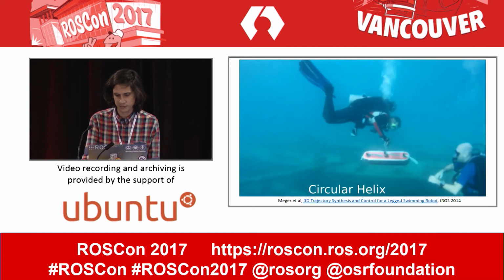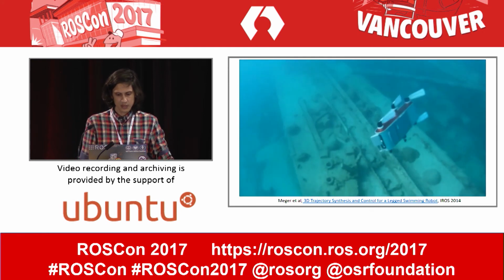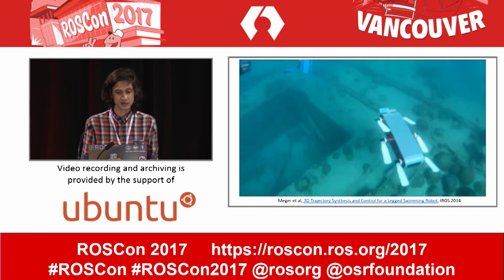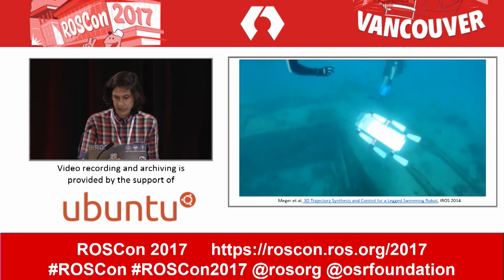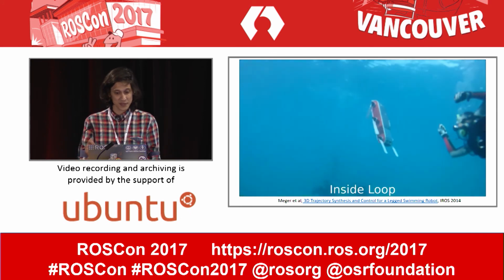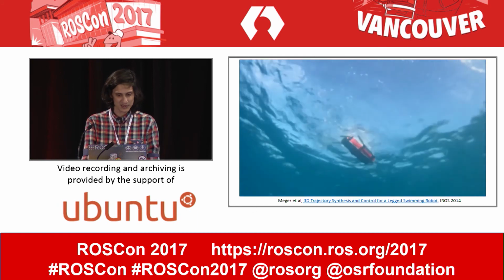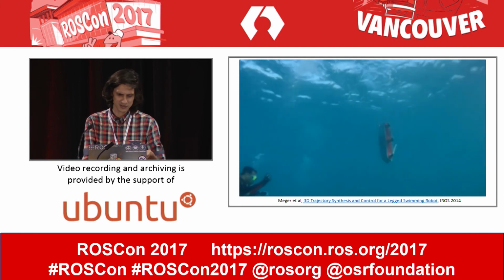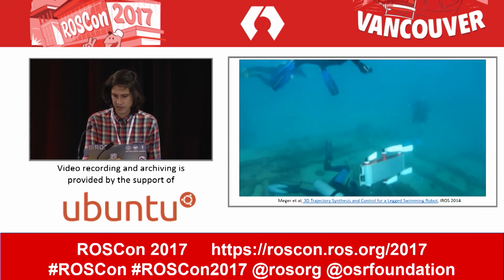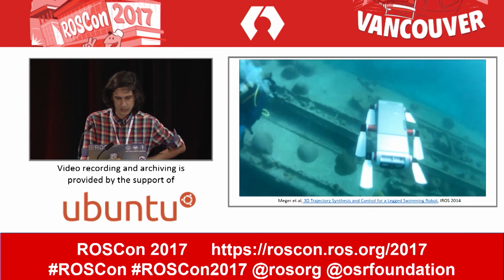So all this ROS-based software has enabled us to, for example, program the robot to perform certain maneuvers to point its sensors in any direction that we want. We can do this using just the autopilot package, but we have to spend a lot of time tuning all the controller parameters to get all these maneuvers. Tuning these controllers probably took, I would say, a couple of days. So that's why we're looking into learning these controllers instead.